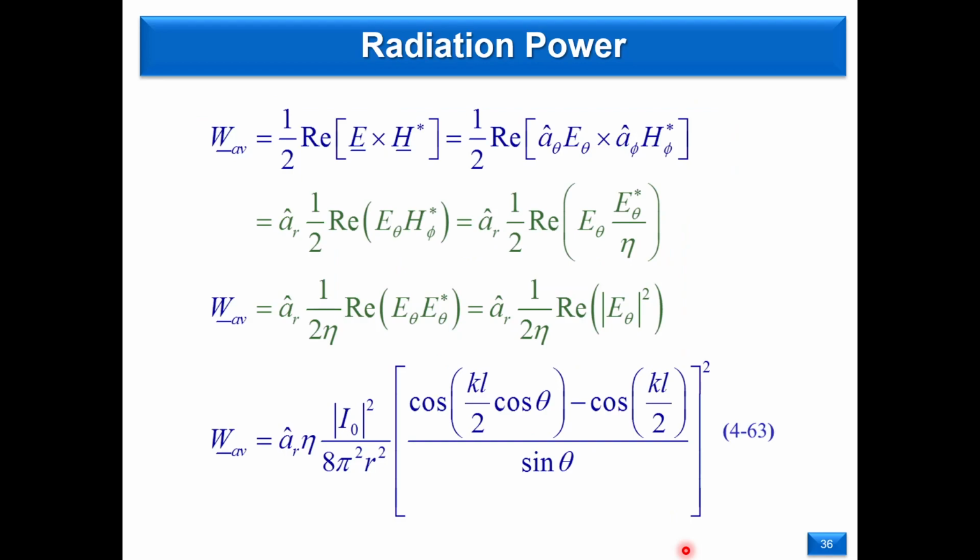Now, in order to calculate the properties and parameters of the antenna, we need to calculate the radiation pattern and the radiation resistance. So we need to find the radiated power. Here again we're dealing with the far field only. The radiated field, as expected, is in the a_r direction. It has this expression, and as I said, it's the square of E in the far field.